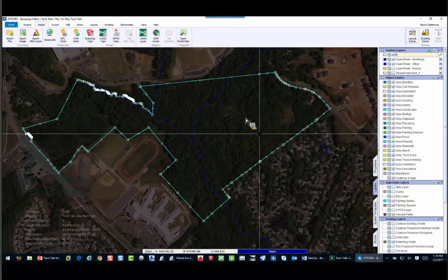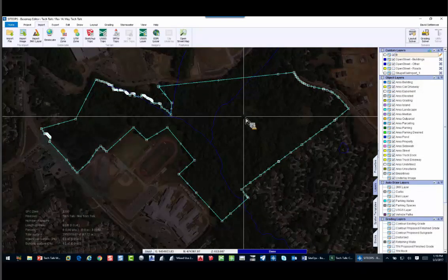We want to do a project. Let's say the zoning says we can have an R4 development, but the client, like most of them, wants to get maximum lot yield, right? Well, a lot of us realize that sometimes maximum lot yield is not always by following the rules. We want to go out, and if we're allowed, we want to do a cluster development. Maybe we want to do a PUD, want to go for conditional use. Again, tons of different ways to get around having to deal with the density on a project.